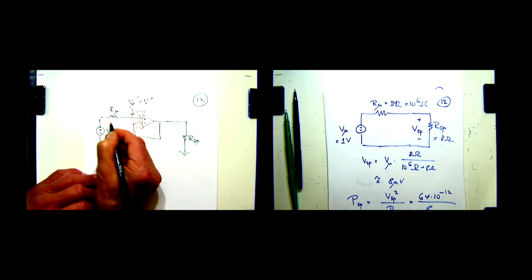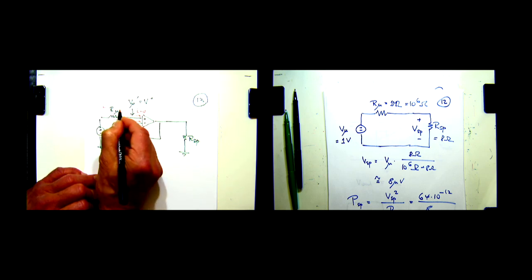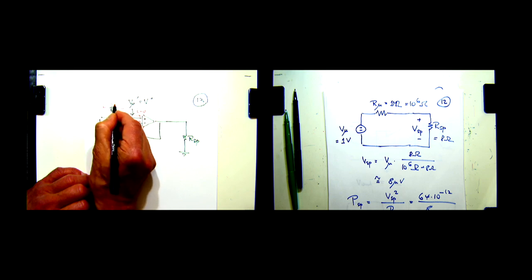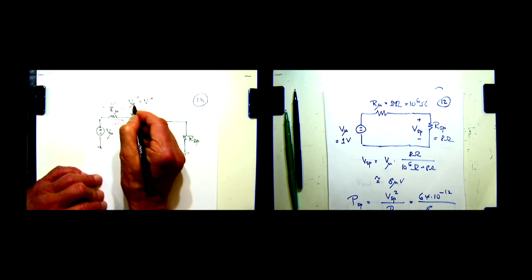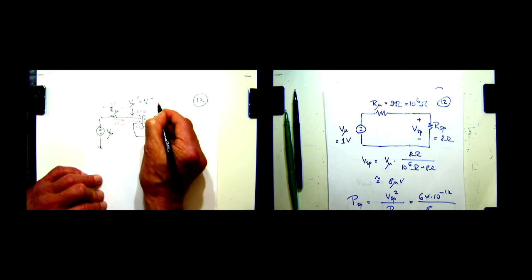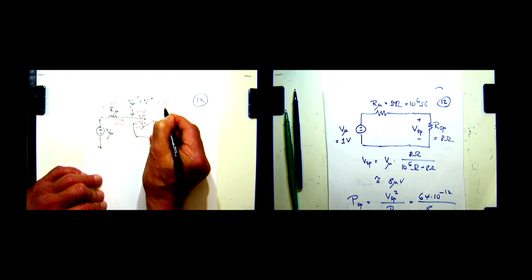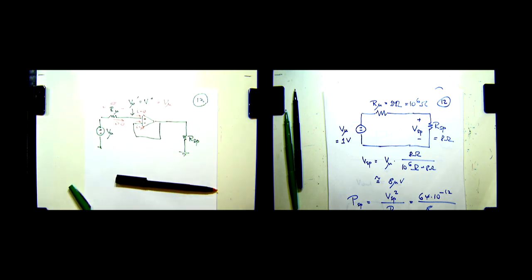Okay? So then this current here is 0, and the voltage across here is 0, and V mu prime is going to be equal to V mu. Microphone voltage. Okay? So there can be a resistor there, but if there is no current flowing, there's no voltage drop, so the nodes could even be just connected together.